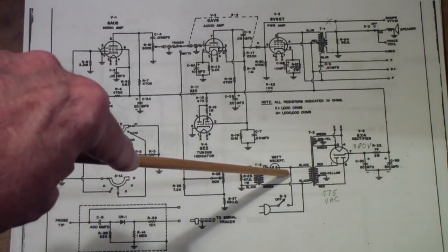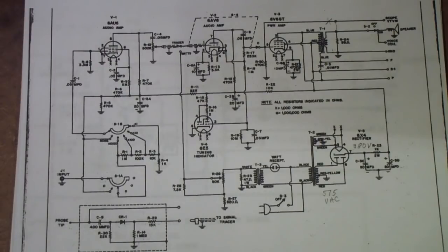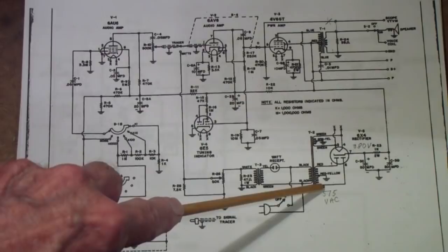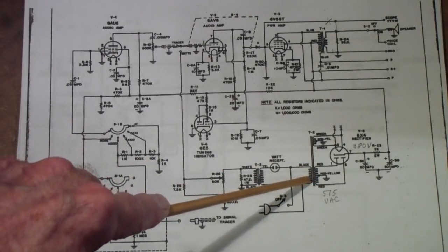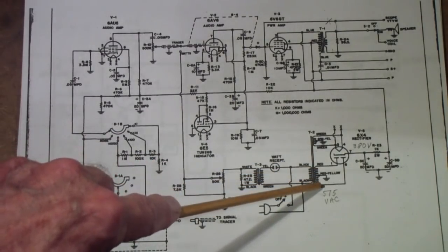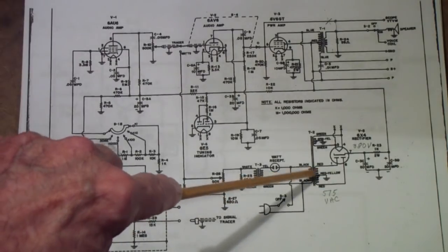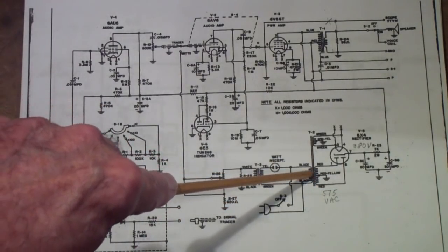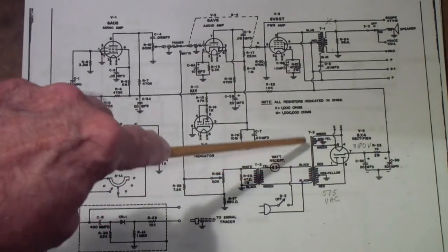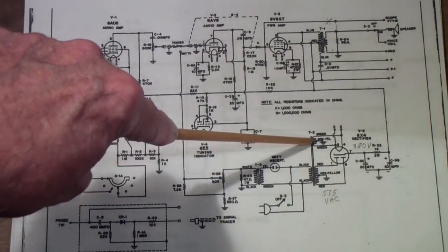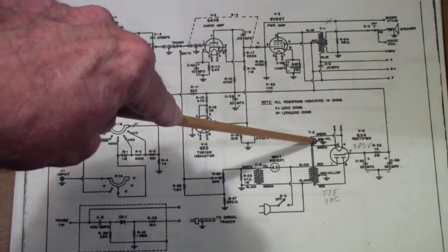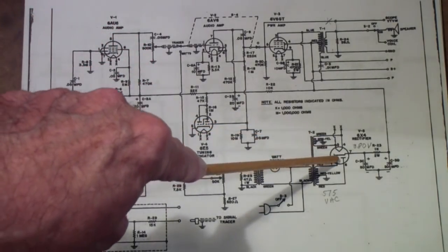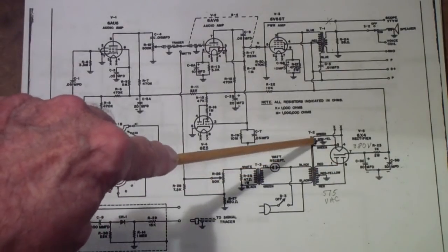Well, I did this for $0 because I took advantage of the fact that I knew in this old signal tracer and in a lot of the old tube equipment, you can find a center tap transformer. Now, you can go out and buy one, but why buy one if you just want to test it? Also, if you wanted to, you could also use the filament voltage from this same transformer to drive the filament of the tube that you're testing.